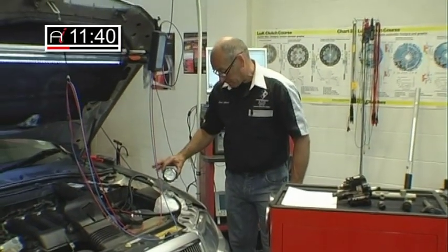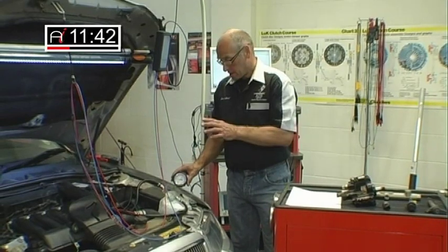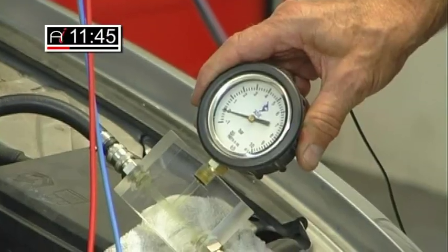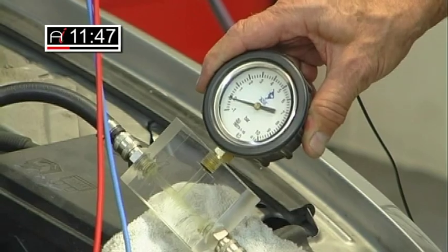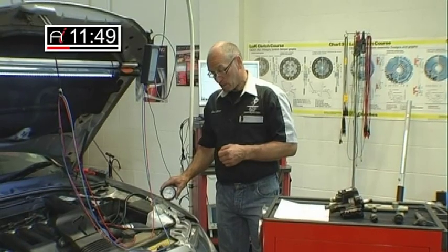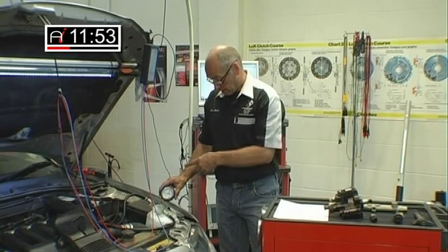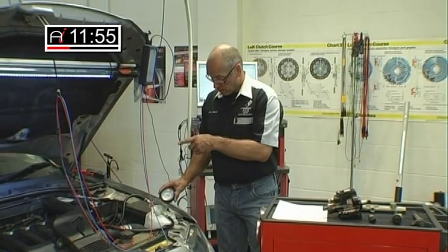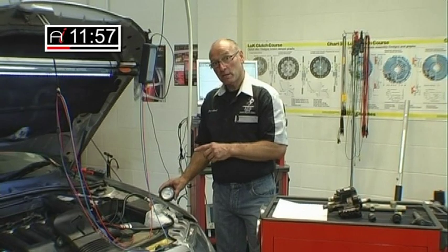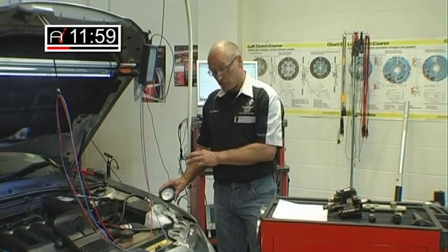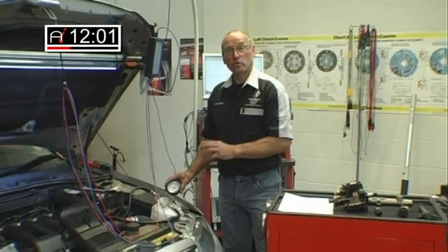As I've explained, in this variation of system, some vehicles have a pump in the tank and an intermediate pump, in effect supplying positive pressure to the high pressure pump, and we can monitor this. We're actually monitoring it after the fuel filter, before the high pressure pump. We're measuring it in real time, actual hydraulic pressure.